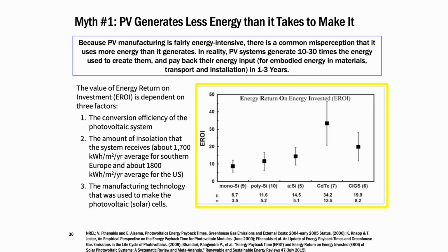So the higher the EROI, the better. This chart summarizes about 230 different research papers on the topic and found that most solar panel technologies have an EROI of 10 to 30 times plus. Another way to look at this is based on energy payback period, and typically solar panels will pay themselves back within the first year of operation.